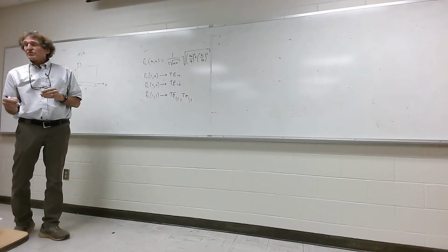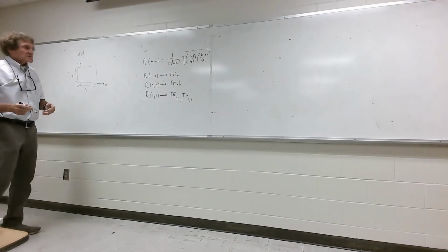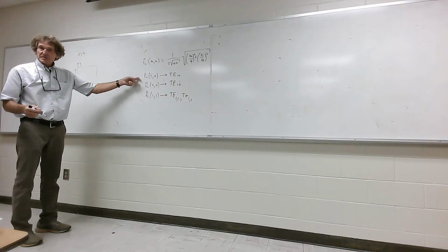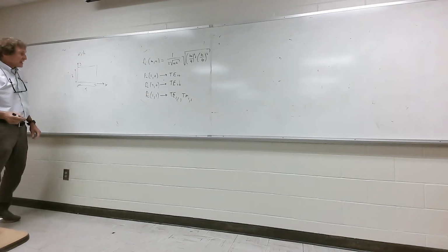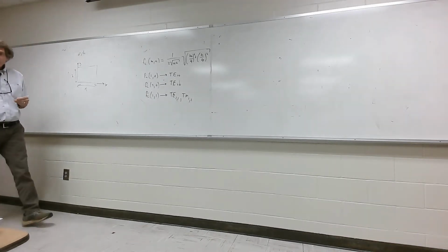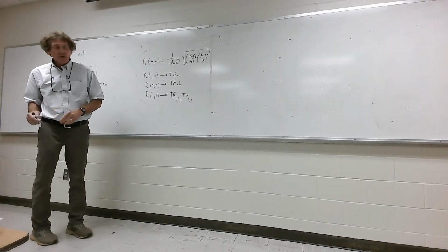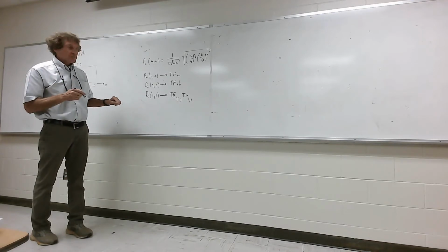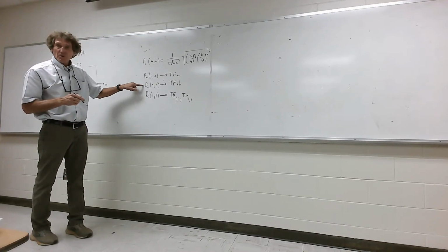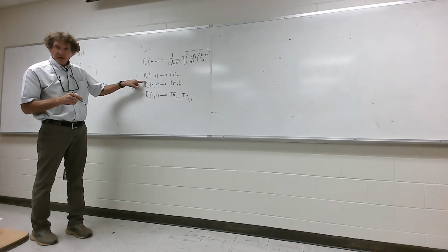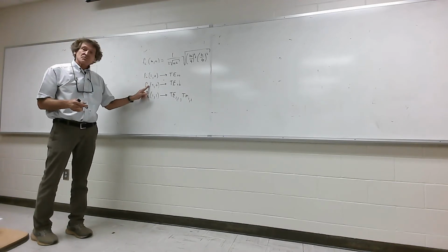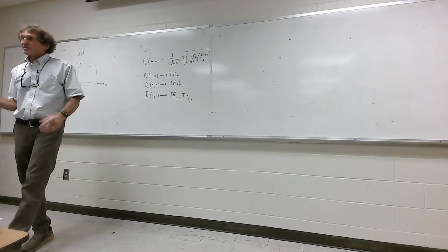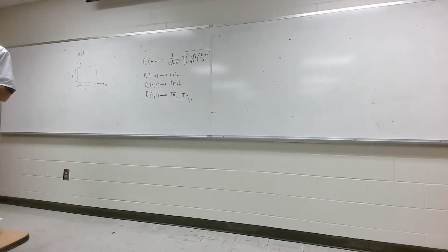So usually, the way you do these problems, and you should always do it, first you calculate the lowest order cutoff frequency, then the next cutoff frequency. Follow me on this? And you find the operational frequency. Now, almost always, but not always, the operational frequency is between the 1.0 and 2.0 modes, somewhere between those two. Do y'all follow me? And the 2.0 is twice the 1.0 cutoff frequency. So it's somewhere between there. If that was 6 gigahertz, this would be 12. Your operational frequency would be 8 to 10 gigahertz typically. That's how you do that problem.